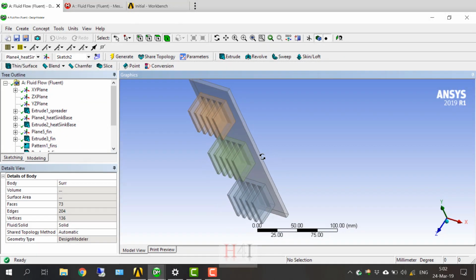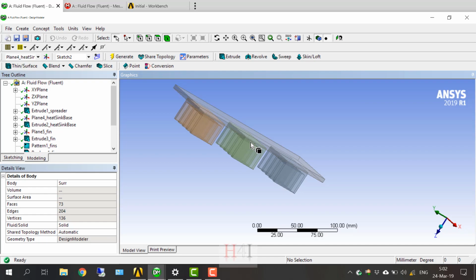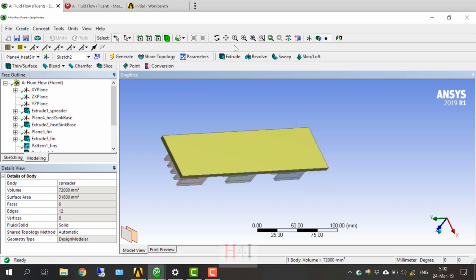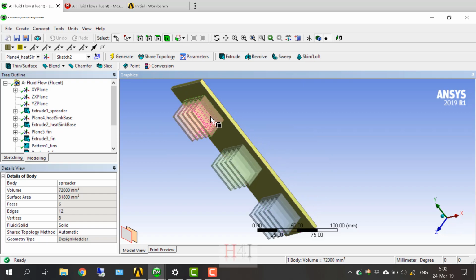This is the domain I'm studying. I'm supposed to have 3 thermoelectric generators I want to cool. The location of the thermoelectric generators is on this surface. On the thermoelectric generator, I use a spreader. This rectangular body is a spreader to spread the heat over a larger surface. And above that, there are 3 heat sinks to dissipate the heat further. Okay, this is the case I'm studying.